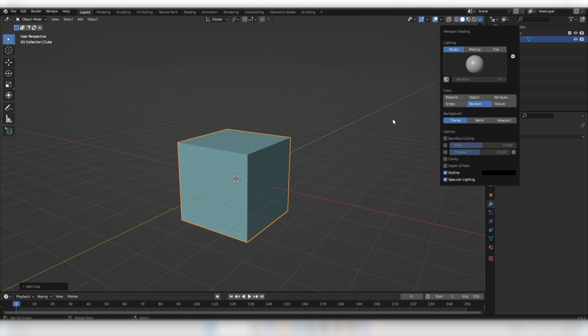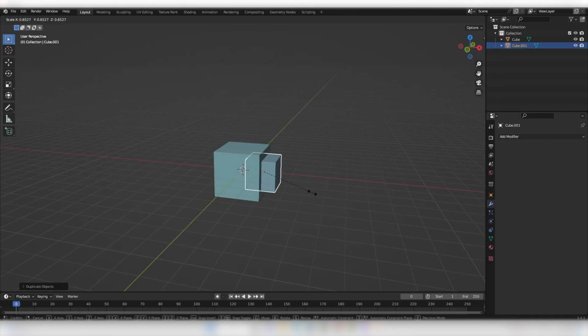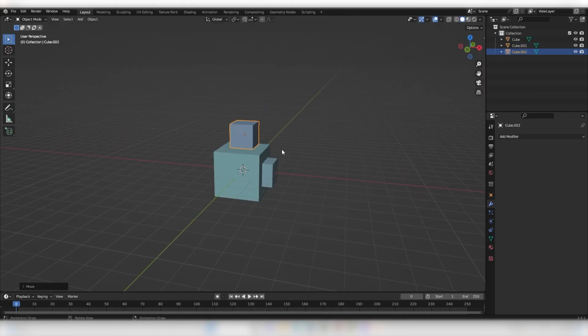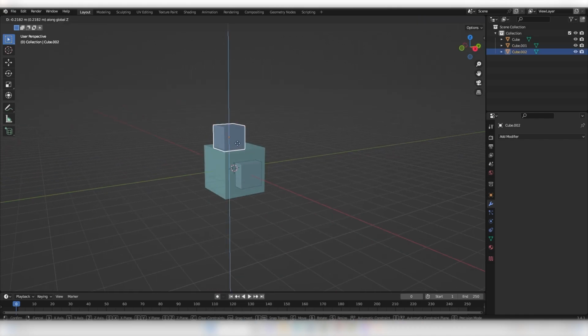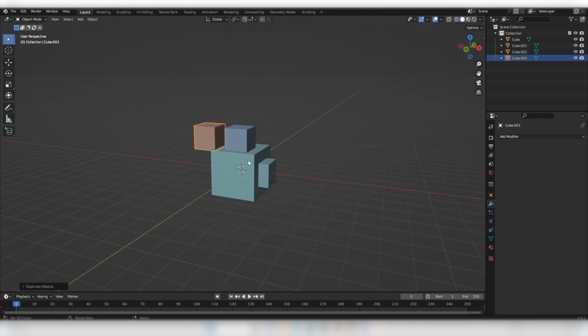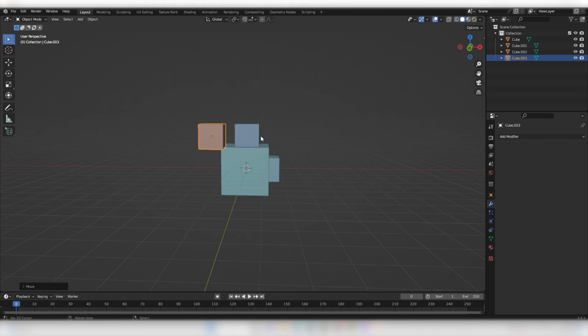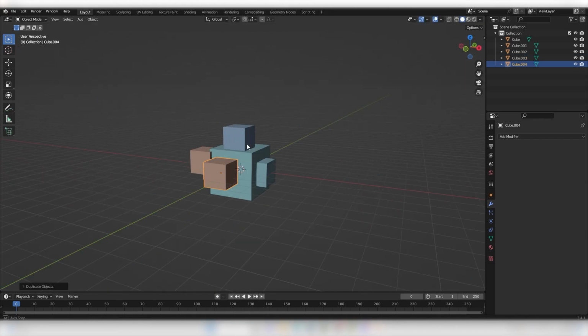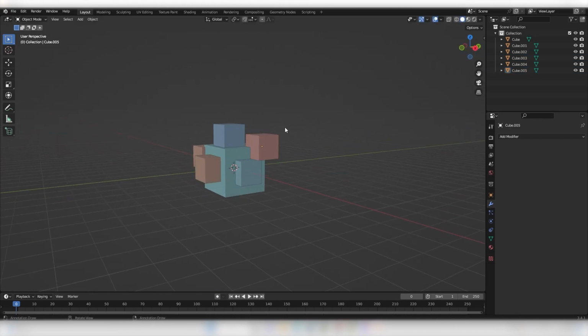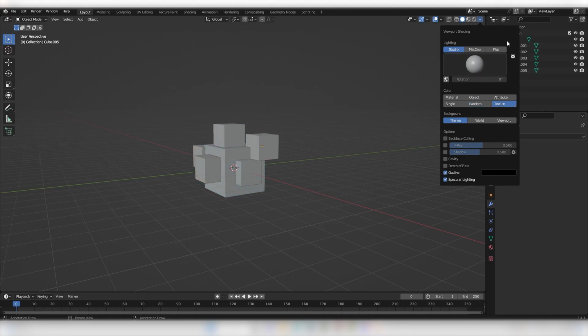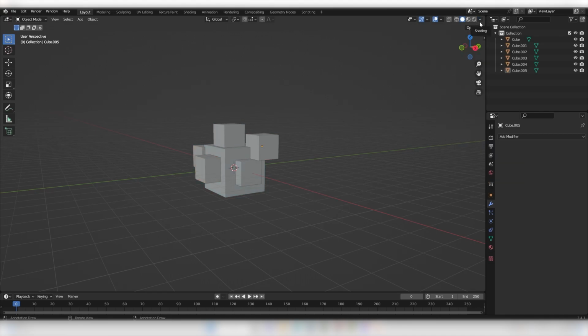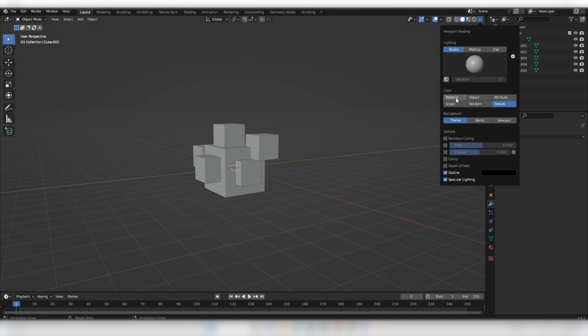And random's always cool if you've got a bunch of stuff in your scene. It will give it all a random color. You can see they've got random colors right now. It picks a random color, so if you've got a bunch of shapes, you have a load of different colors, which is pretty cool. I usually use texture mode when I am modeling just because I often use textures. However, material is always good enough. And if you come down here now, there is a lot more settings.